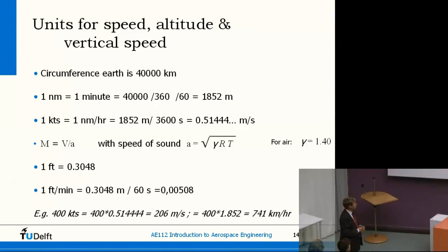So with most aircraft, you need to stay under the speed of sound. So it's mainly important to avoid going beyond a certain Mach number, also because of the load on the aircraft. The equivalent airspeed doesn't really work anymore. As soon as the shock waves play a role, you cannot express your maximum speed in equivalent airspeed, but you also need to cover the Mach number. So at some altitude, your maximum speed is determined by your Mach number and not your equivalent airspeed anymore.